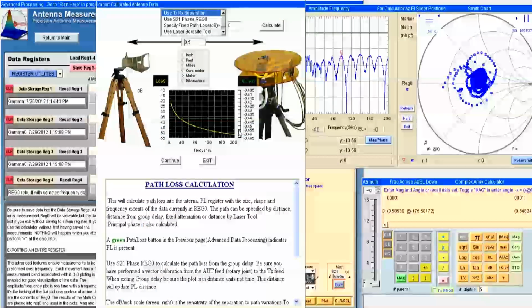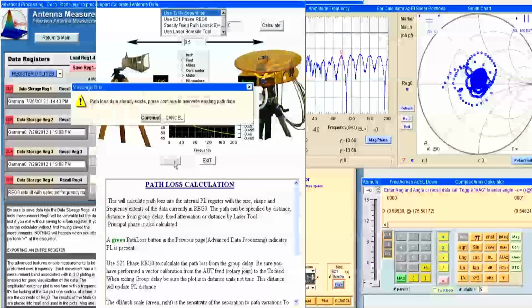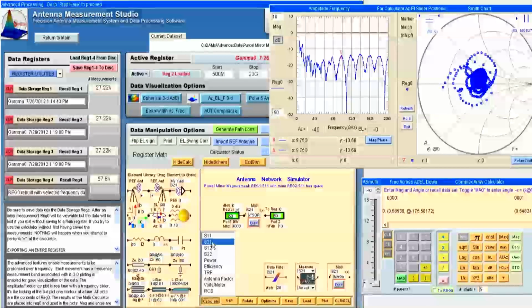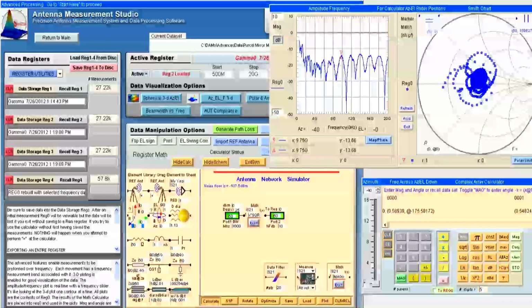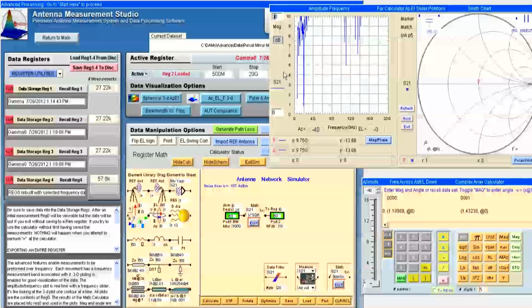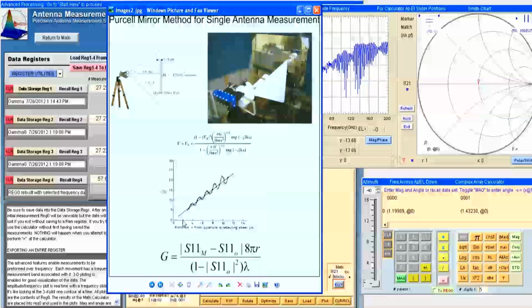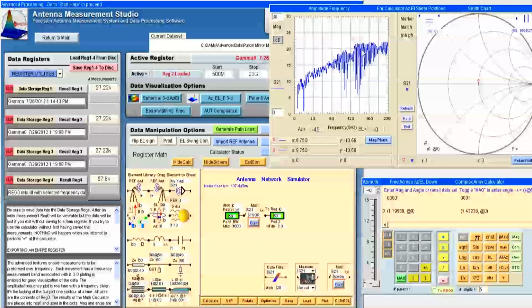Next, we'll generate the path loss at 0.5 meters from the horn phase center to the mirror. We'll then calculate the S21. We need to rescale the plot from 0 to 30 so we can see the DE726 horn profile. We also notice a considerable amount of variation as was originally present in the original analysis. Those variation widths between these points represent multiple reflections inside the chamber from the mirror to the horn.